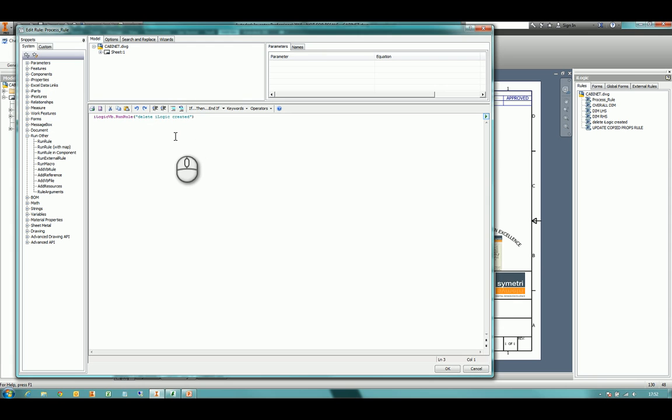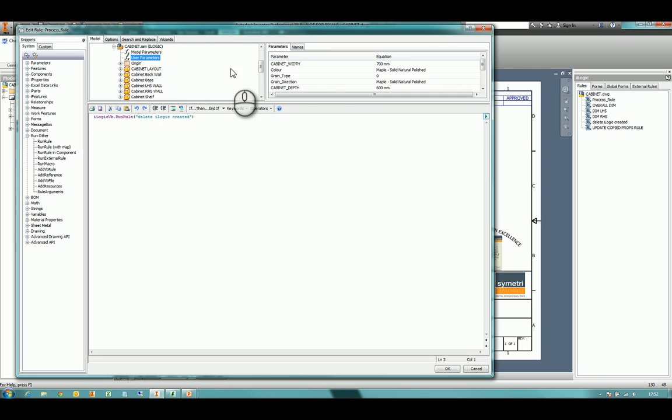Next thing I want to do is decide on the value, and based on that do an if statement. So if I drill down into my rule, look at my user parameter, I can find my parameter that has door location. You can see that there are three options. Right click, capture current state. That brings me in the parameter with the name. So I'm going to say if parameter door location is both, then do something.